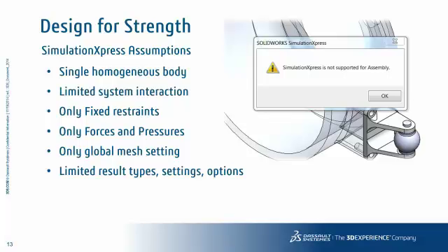Limited system interaction, to me, like I said, is if I have an assembly, there might be some more complex interactions, such as contact pressures, bolted fasteners, frictional contacts, that I can't take into account because we're kind of fusing it all together into this one massive body.